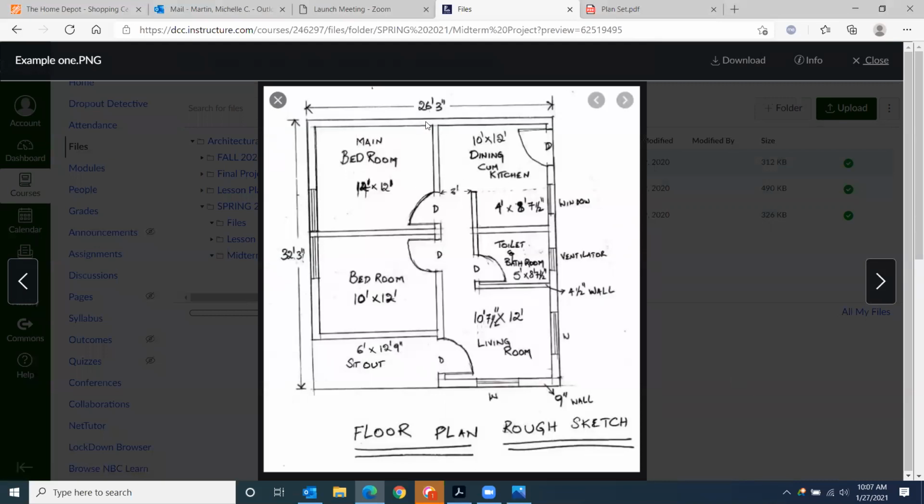Once again, here, 26 foot 3 inches. Here, granted, it's easy to tell that this is 12, but sometimes I think it's just easier to lay this out at like a 12 foot and a 10 foot, which is how we would do it in Revit, and then 14 foot. Once again, you want to get the dimensions from this wall to the interior, this window opening, the window opening size, and then what the dimension would be. Obviously, this is flush to that window.